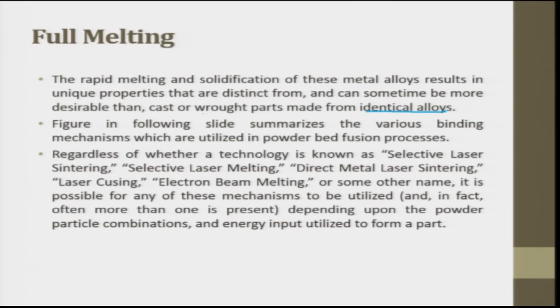In the next slide, we will show the summary of the various binding mechanisms which are utilized in the powder bed fusion process. Regardless of whether a technology is known as selective laser sintering, selective laser melting, direct metal laser sintering, laser fusing, electron beam melting or some other name, it is possible for any of these mechanisms to be utilized depending on the powder particle combination and energy input utilized to form a part.